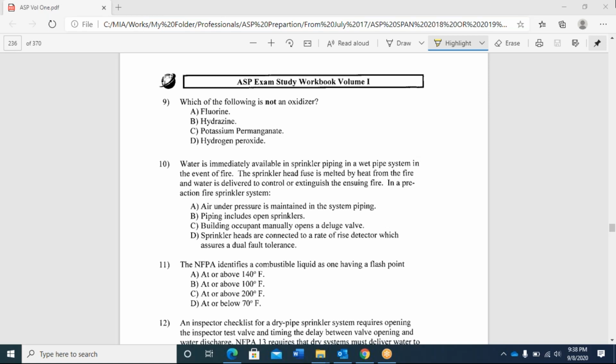And generally, we are using this on site. If you don't have a water reservoir upside, the water is not coming directly by gravity. So we install our tank at the downside level, very near to the toilets, and we install that pump. I forgot its name, but once the pressure inside the pipe reduces, it starts automatically and creates that pressure. So again, if you open the tap, it will start again. We need to check the name of that pump. We call it the jockey pump. Okay, that is the jockey pump.